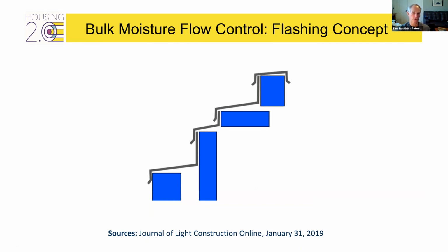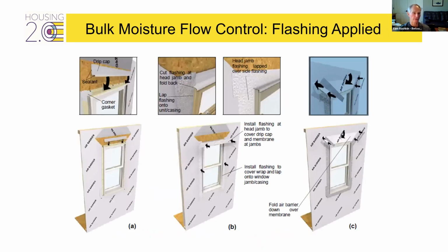It's basically doing a couple things. One is shingle fashion, taking moisture from one component to the next component, and then having little bends where one cap goes to the next. So you can break the cap, can have a capillary break to stop water from siphoning up. And then in shingle fashion, with certainty, the assembly will dry, or the water will shed, and you'll keep a dry assembly. And that's how we develop these details we show you for, let's say, a window opening. It's all using that shingle fashion strategy.